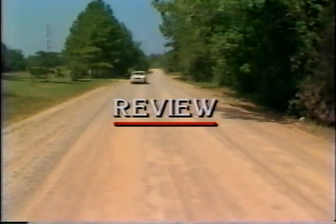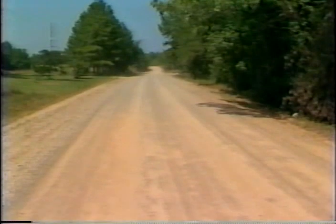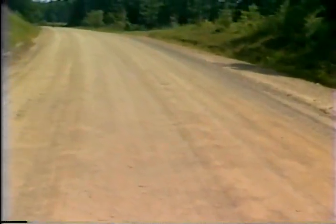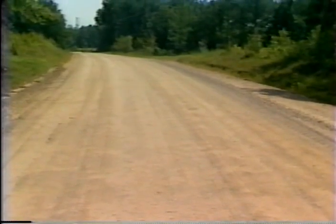We will now briefly review maintenance of gravel roads. The importance of gravel roads and the need for their proper maintenance has been discussed. A good gravel road has a hard crust formed on the surface of the road to carry traffic and to shed water from the surface. This crust is formed by a combination of large aggregates, smaller aggregates, and fines mixed together and compacted under traffic.